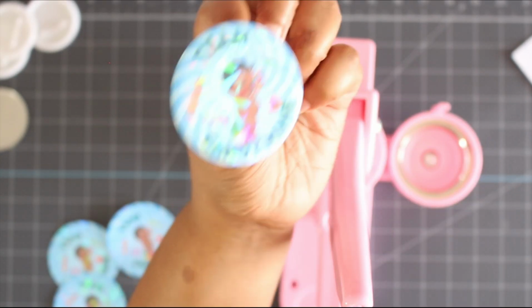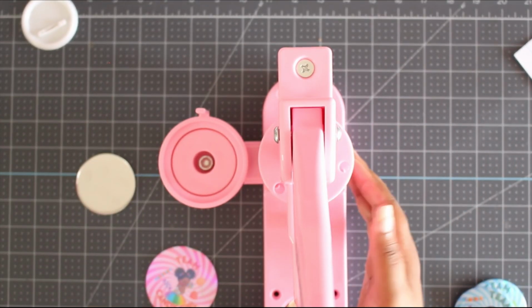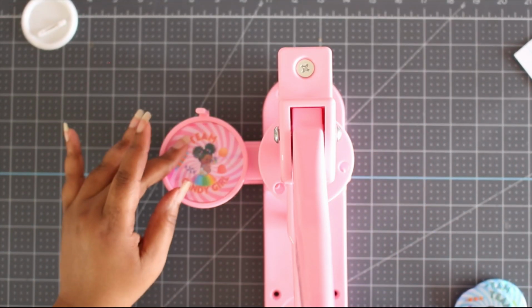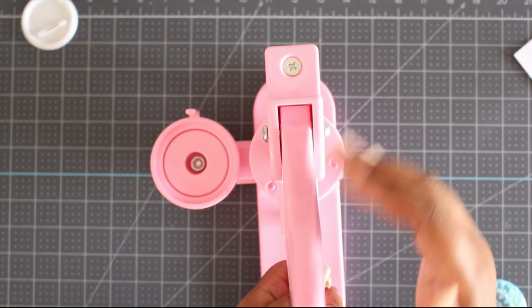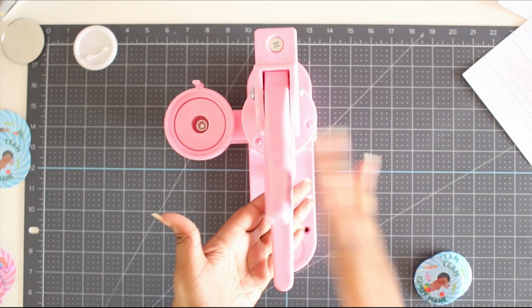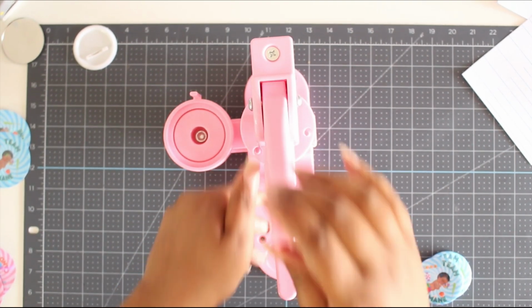So let's do it again with the girl. So we're going to start with our Pinback. We're going to push it, add our silver, add our design, push it over, squeeze until a click, push it again. You're going to squeeze it until the top lever touches the bottom,